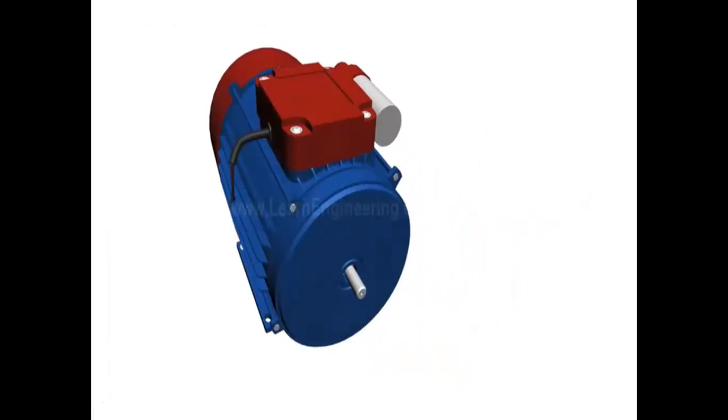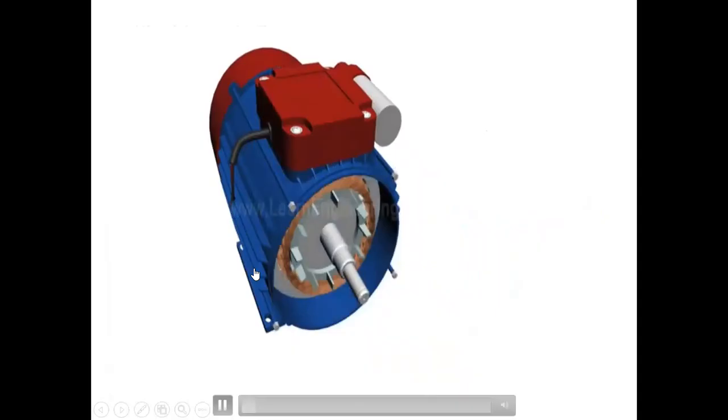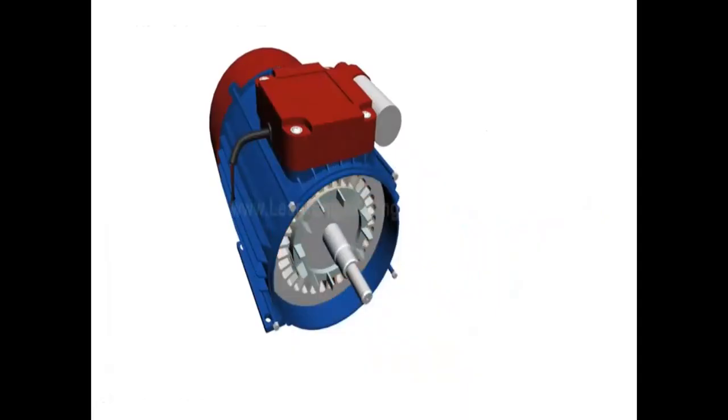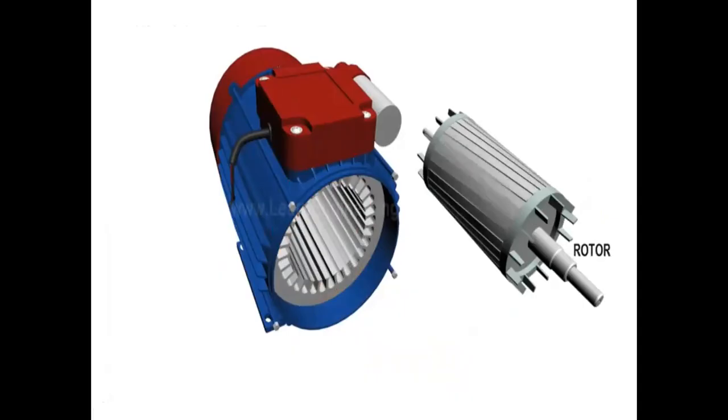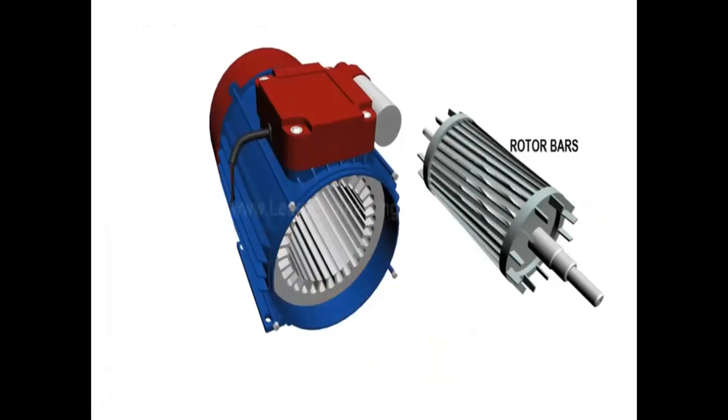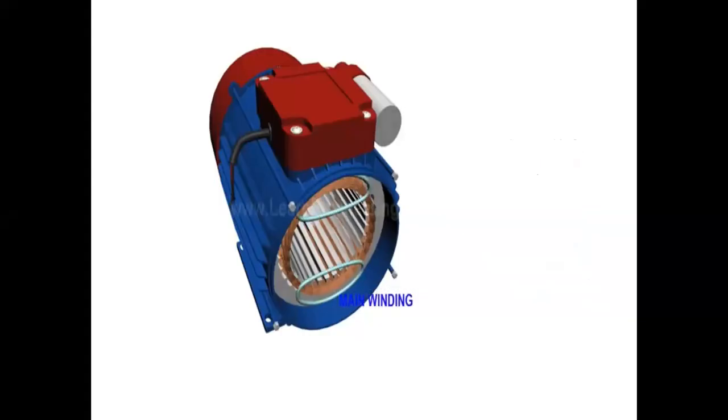So to be able to understand that, let's consider this animation. We have already said the external structure is the same. The internal structure of the rotor is very similar to that of the three-phase induction machine. However, the stator winding is single phase. In a commercial machine, there's an auxiliary winding to help start the machine, and a capacitor. We'll be talking about why we need the two.